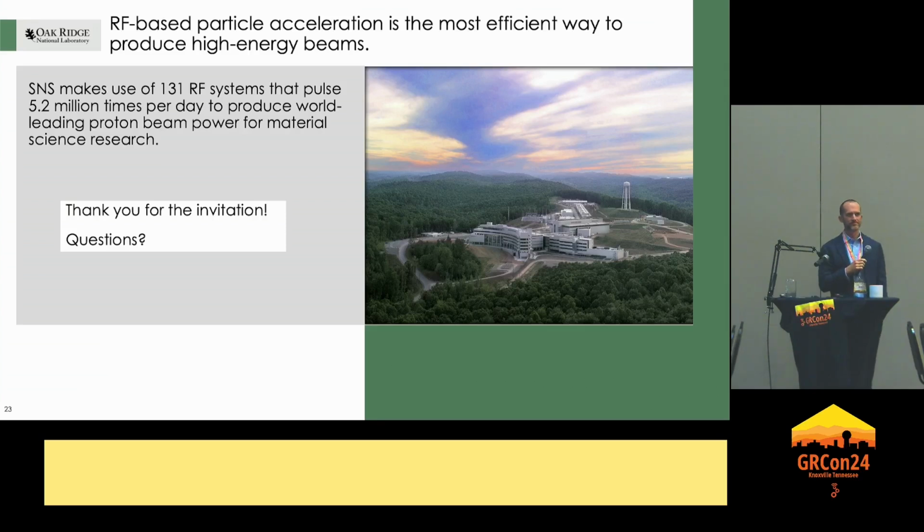What kind of sensing do you have to have in the loop just to know that things are going as expected? So your question is about sensing? Right, since it's a closed system in operation. Sure. So specifically for our RF, we basically measure power, right? We look for arc detection, just light, right? We have fiber optics that look at certain points, especially the high power side. We look for arcs, we monitor vacuum. Obviously we have to have the entire accelerator under vacuum.